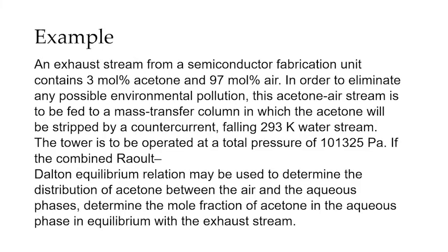Let's try this example. An exhaust stream from a semiconductor fabrication unit contains 3 mole percent acetone and 97 mole percent air. In order to eliminate any possible environmental pollution, this acetone-air stream is to be fed to a mass transfer column in which the acetone will be stripped by a countercurrent falling 293 Kelvin water stream. The tower is to be operated at a total pressure of 101,325 pascals, or atmospheric pressure. If the combined Raoult-Dalton equilibrium relation may be used to determine the distribution of acetone between the air and the aqueous phases, determine the mole fraction of acetone in the aqueous phase in equilibrium with the exhaust stream.